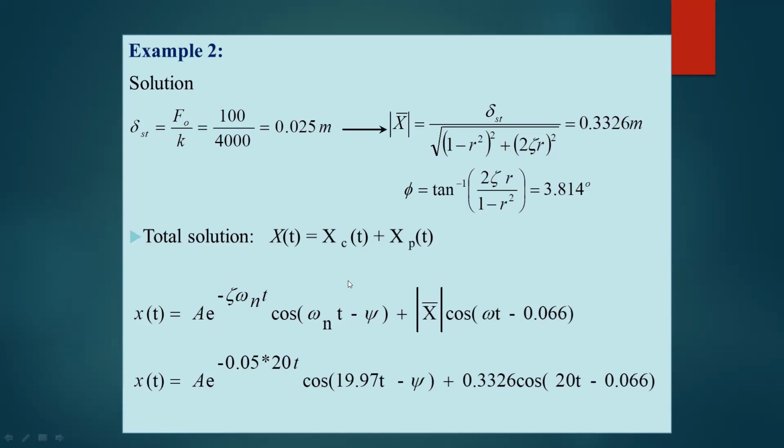the condition of higher external frequency. To overcome higher external frequency, we need some kind of excessive mass. To overcome lower external frequency, we introduce good stiffer material. And at the point where resonance is expected to occur, we consider a material with a good damping coefficient. So this is the way we can identify, especially in the critical region.